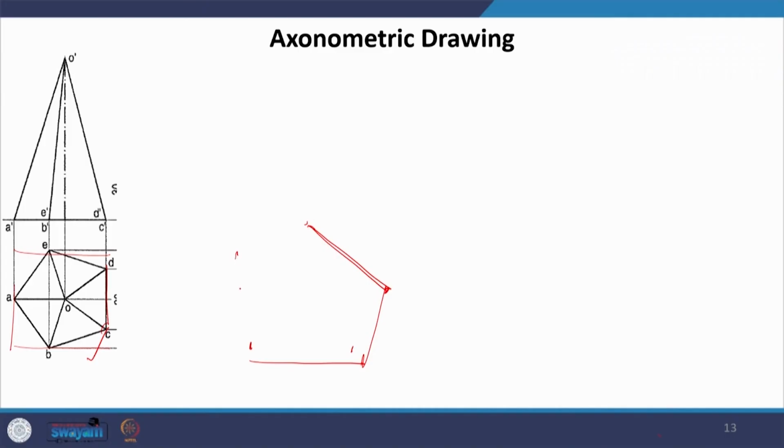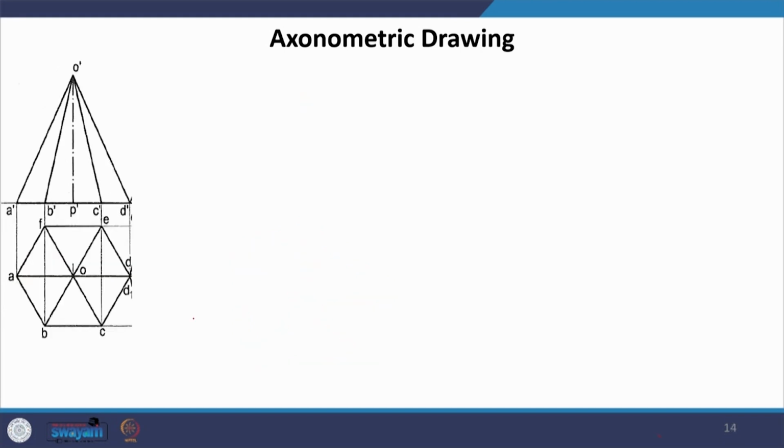This is again the same thing, just the pentagon rotated. So, you have to start by drawing this 45 degrees line. I am assuming that this is how we are taking it, and then you can take the same angles, or you could make a reference for easy drawing, or you could just draw the pentagon with this as a side. So, you will arrive at the same base shape, and then you can just extrude them. You can also arrive at this point O, extrude it and draw the pyramid.